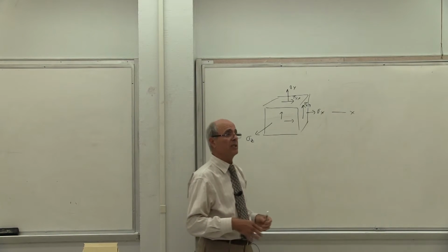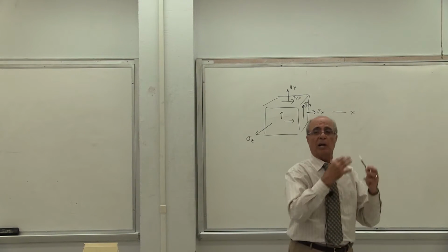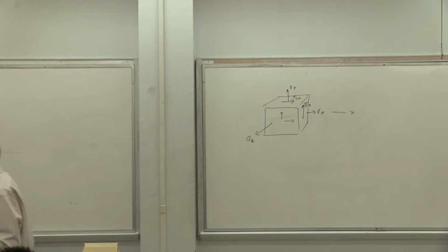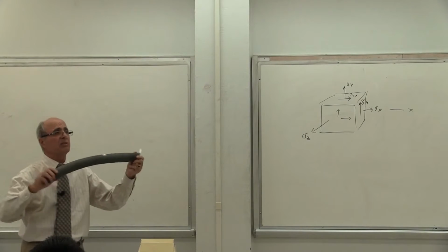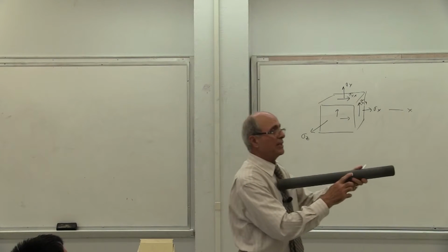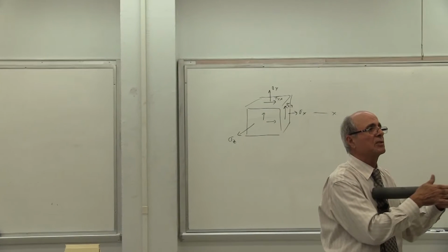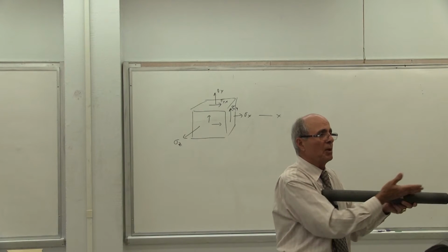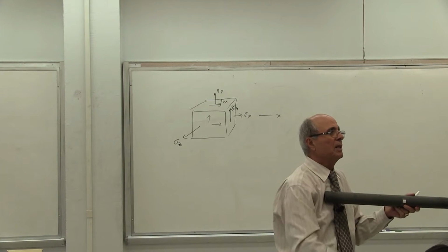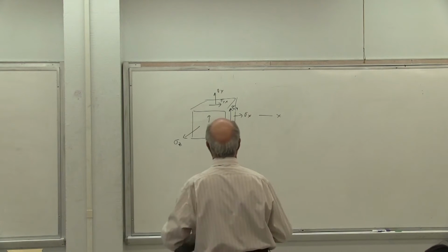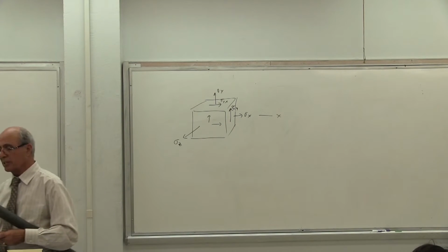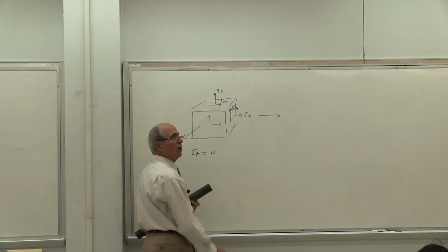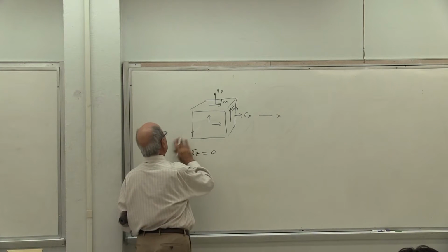However, the way we design it, the object still is 3D, but we are assuming everything is on the surface. Everybody understand that? I have brought this up many times. When this is a shaft or a beam, this is a 3D body. However, when I look at this part, it looks like a plate, so we call it plane stress. It has sigma x, sigma y, but nothing coming from the z direction. Therefore, remember that all your undergraduate stress analysis is on the basis of sigma z being equal to 0.